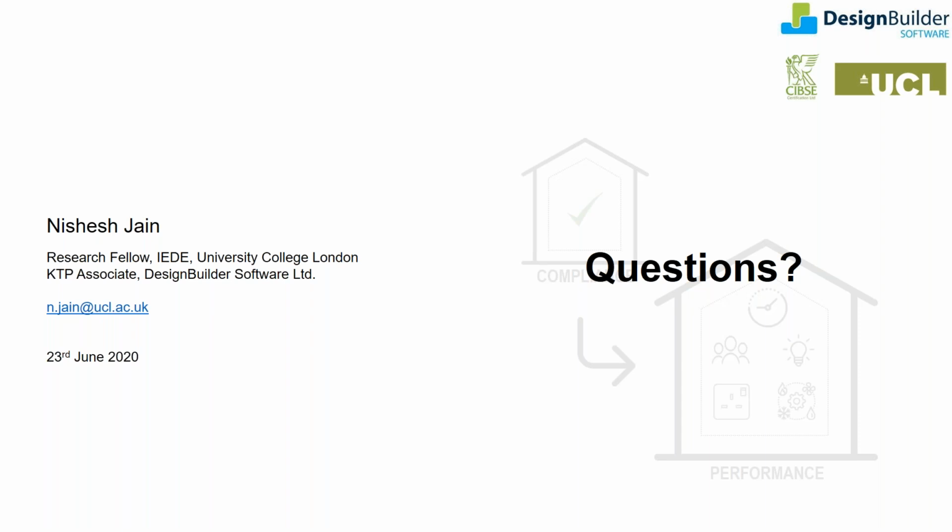To do a similar thing for a particular building, I would say for small projects you would want to do detailed modeling, which would be building physics based, because if your intention is to understand how the building would be performing, how the temperatures would behave, a building physics model looks at so many variables at one time. A mathematical model would be designed to look at, say, just energy use, but at the same time you can't look at what's happening with the thermal comfort. So these types of trade-offs need to happen.